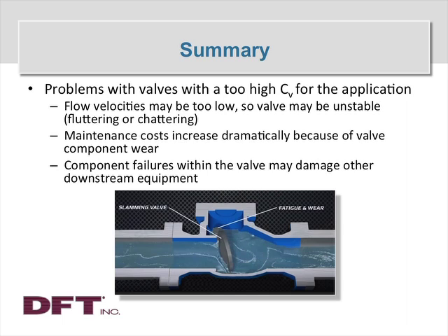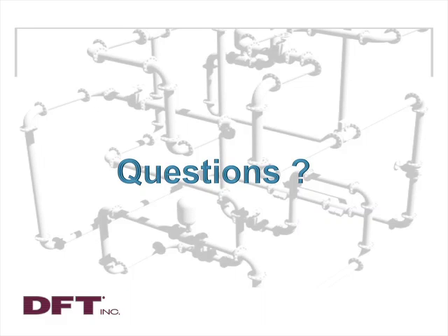And when that pin fails, that disc can go downstream with the fluid flow in a worst case scenario and either hit the next valve or flow meter or get wedged into the first 90-degree elbow, and you're going to have a difficult time fixing that problem and getting the components out and fixing all the consequential damage that occurs. Well, I hope I've given you a lot of good information to consider, but haven't overwhelmed you.